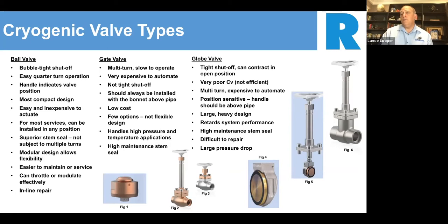Something to remember, and you see this a lot in the industry, when you see an extended stem valve and a short stem valve, and if they're both in cryogenic service, a lot of our valves are rated for cryogenic service, -320. An extended stem valve is a valve that you would put into a line that's seeing cryogenic liquid on a regular basis.